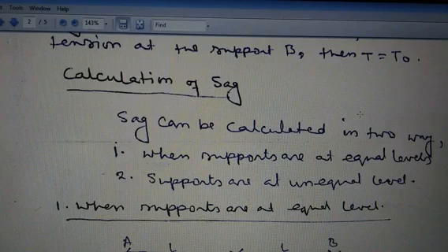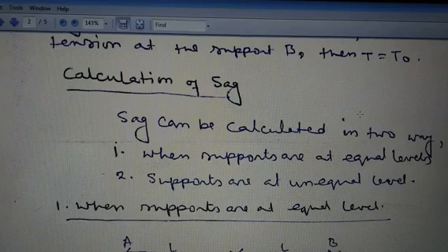The tension is governed by the conductor weight, the effect of wind, ice loading, and temperature variations. It is standard practice to keep the conductor tension less than 50% of its ultimate tensile strength. That is, the minimum factor of safety with respect to the conductor tension should be 2, that is 50%.